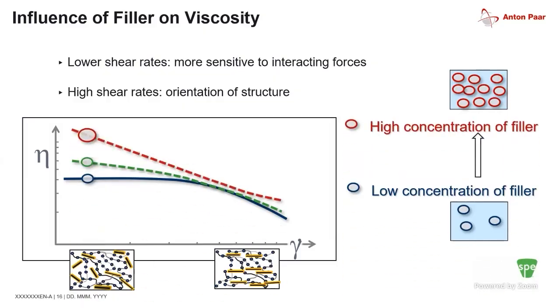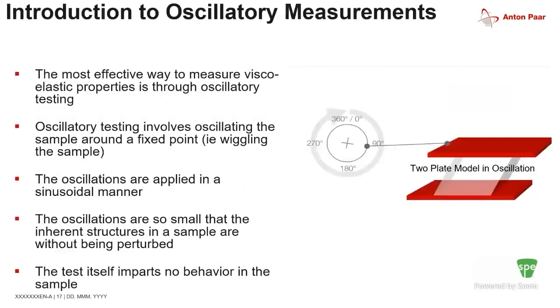Eventually, though, if I have a high concentration of the filler, I get a much higher viscosity, so it requires more pumping to get it to start flowing. And if I have too much concentration, you can start to see that at higher shear rates, instead of a plateau, the viscosity starts to trend upward, showing more of a dilatant response behavior. So again, these are all things to look at in terms of the interactive forces in your material.